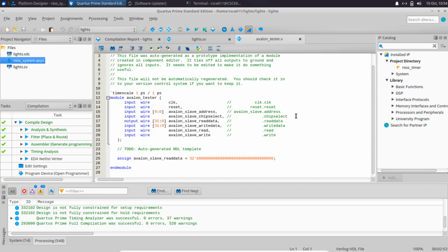This is important because in Verilog, first of all, there's no logic. You can't use logic. A signal declared as a wire can only be driven by structural code, like another module's output port, or an assign statement. If, however, you drive the signal with an always statement, you have to declare it as a reg instead of a wire. And if you make that mistake, you'll get an error message when you go to compile. But it's easy to correct it once you get the error message.